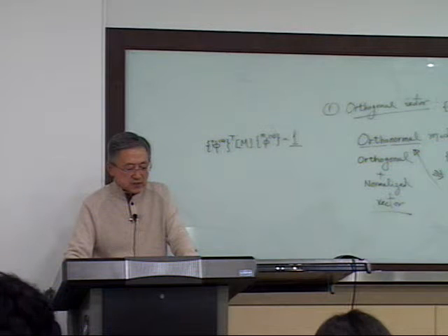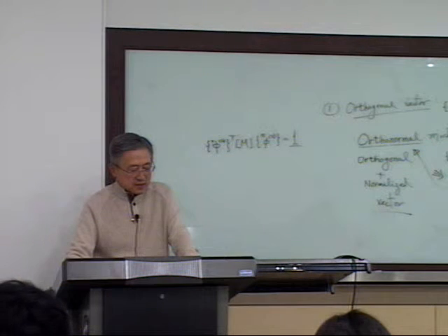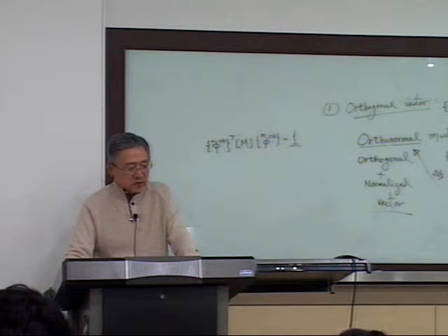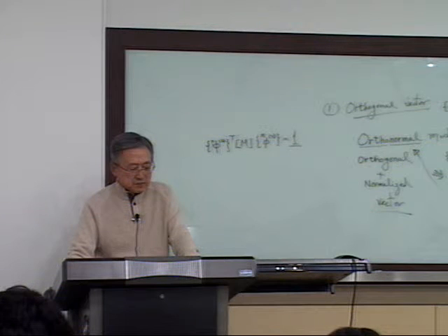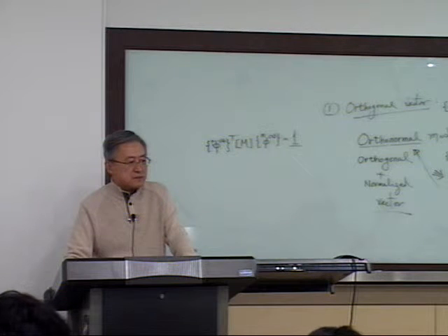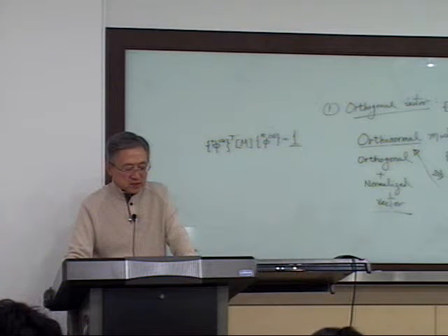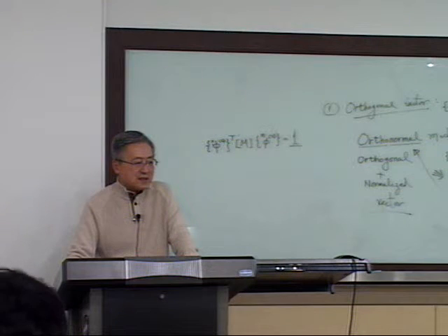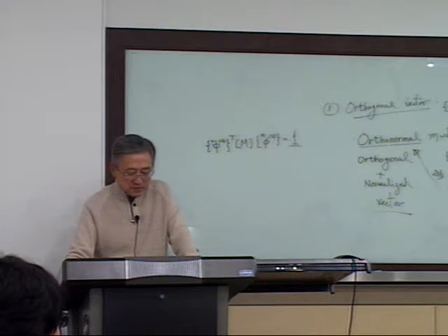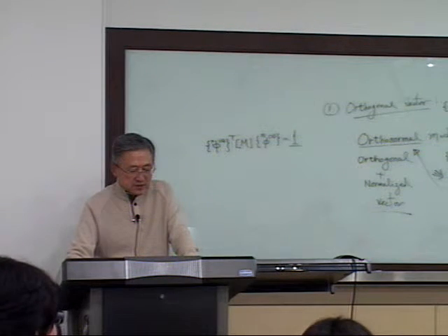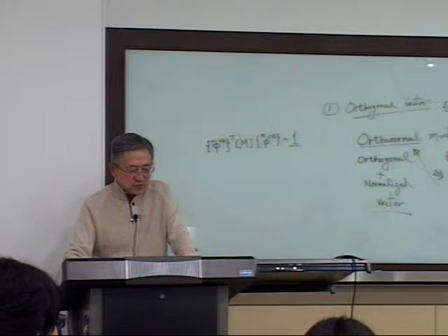But we know the eta j expression is like that. Then y double dot is phi times eta double dot. Phi is a matrix. Every column is like the first modal vector, or mode shape vector, second mode shape vector, all the way through m, which is lower than n. I have a reason coming soon. Then y double dot is this, phi times eta double dot. And it's just the same thing.